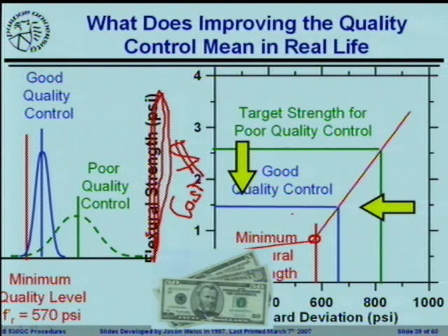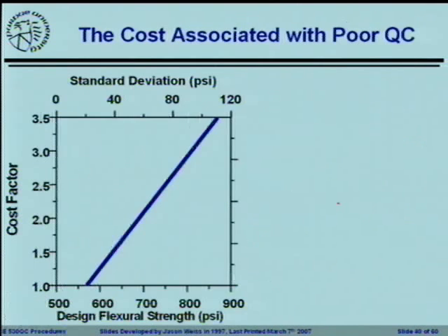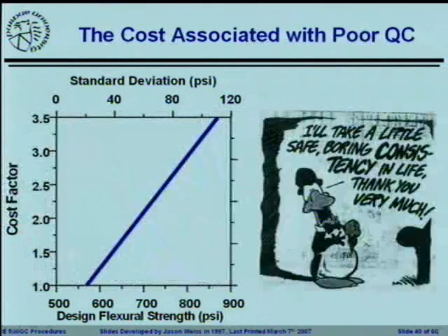You want to try to reduce cement. You want to try to make your aggregates more economically efficient. That's essentially the direction you want to go. This is the cost factor number that we were taking off the previous graph. And as you start to design for higher and higher flexural strengths, you'll see the cost of that mix starts going up. And you can get information like this.